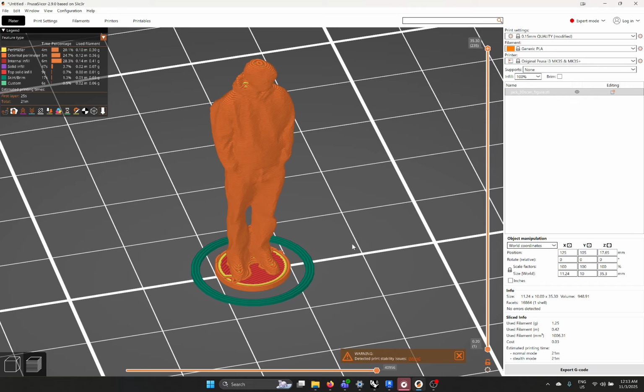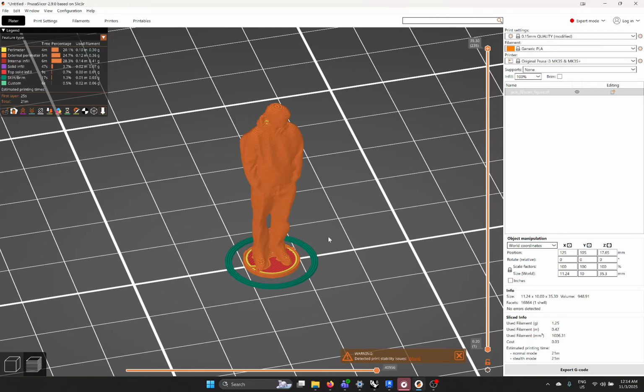because if an object is too big in the 3D printer software, like the size of a person, obviously they can't fit on a printer bed. You might not be able to import that file. So definitely scale your figures before you bring them into your 3D slicer.